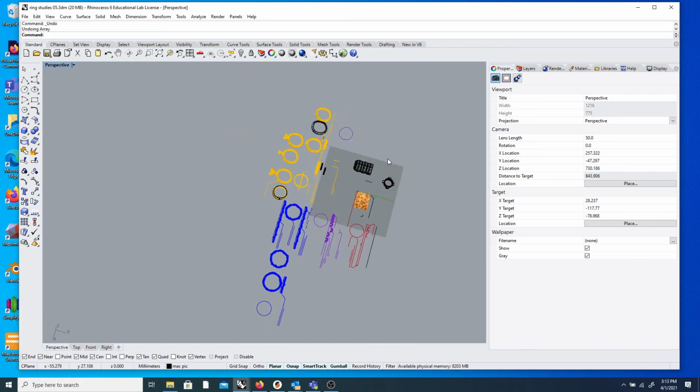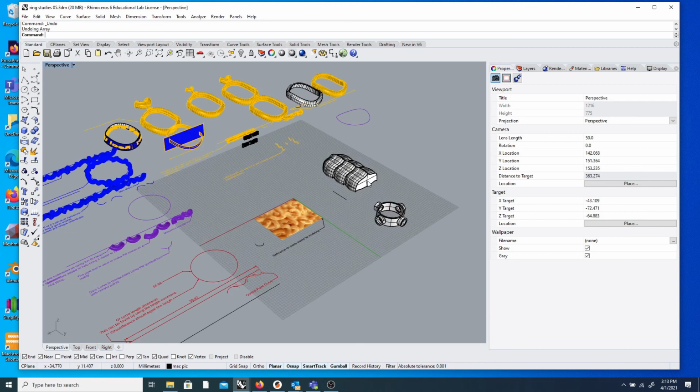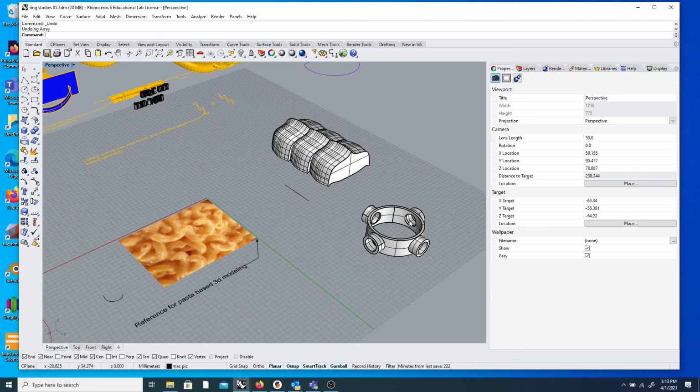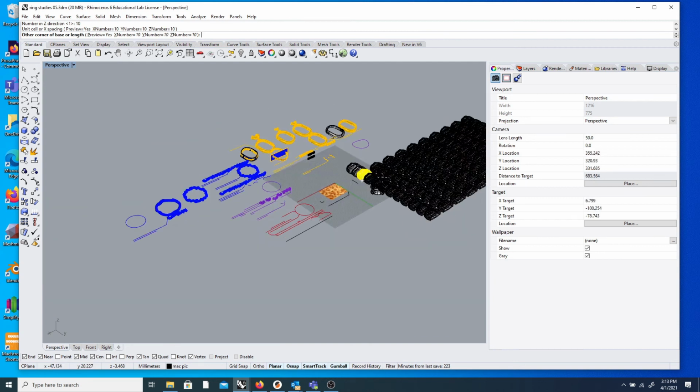So Scott just did a way better job of explaining that than I would have. So array, thanks Haley, is for multiples and how you want to arrange them. You've got polar, which is polar coordinates, and then you have normal array, or just array, and that does it in X, Y, and Z. So if I wanted like a 10 by 10 by 10, so this is my spacing now, and I've got this army.